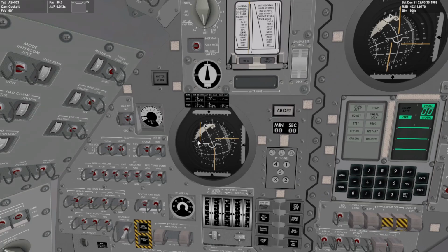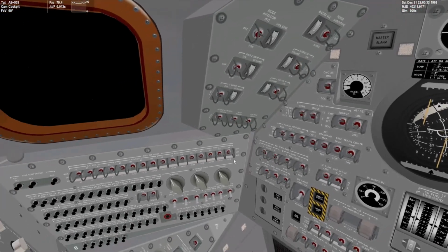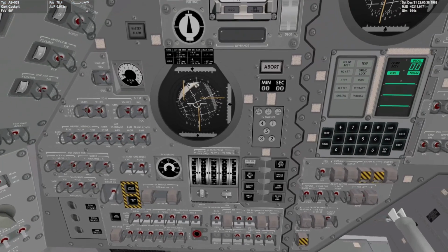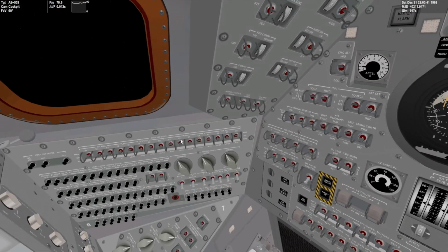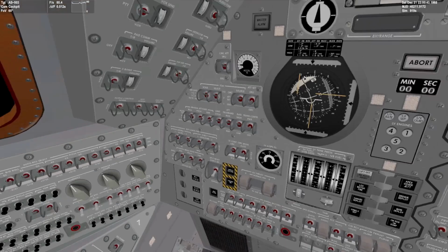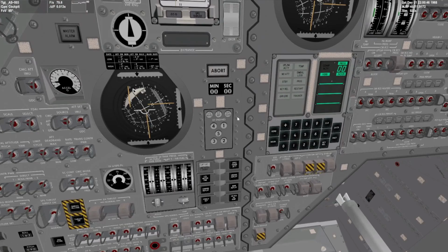and resume the roll using the procedure here. But remember that your thrusters have been disabled on this panel here. So if you do need to maneuver around, be sure to re-enable them. Generally, if you drift too far out and you need to stop what you're doing and restart PTC from scratch, just go into the checklist MFD and manually rerun the entire PTC procedure from start to finish. That way you can be sure that all of your switches are going to be in the proper position, your DAP is going to be configured correctly, and everything will be hunky-dory.